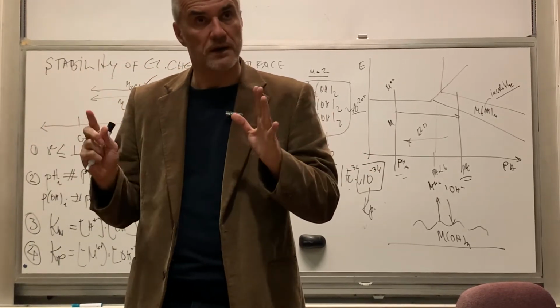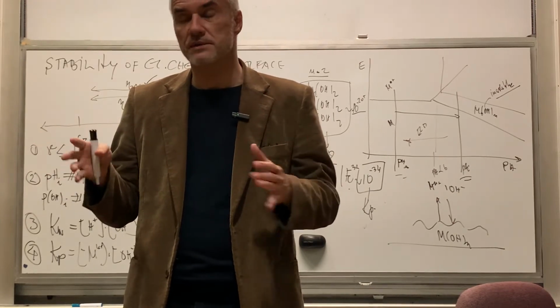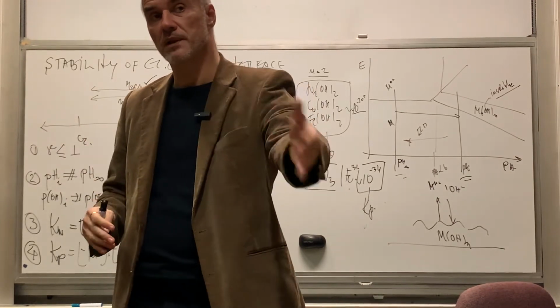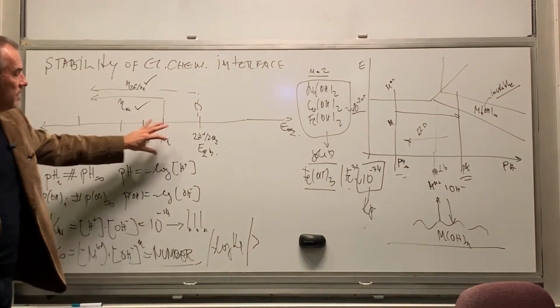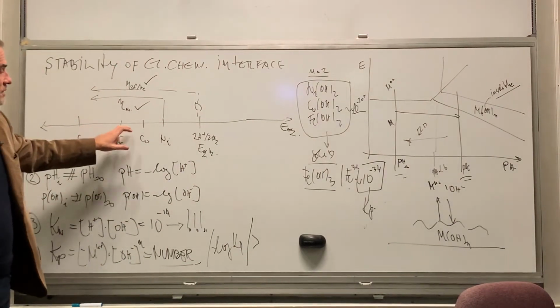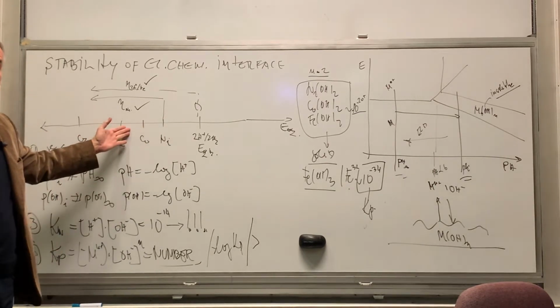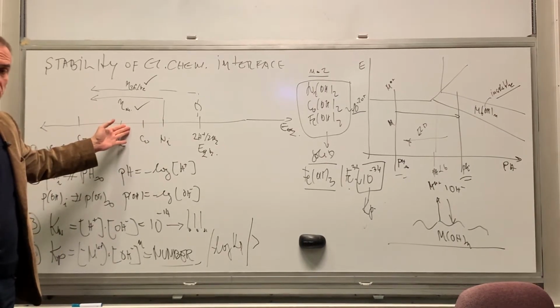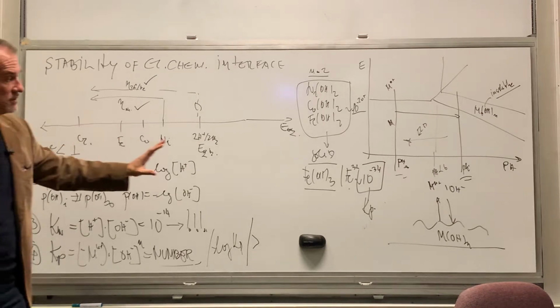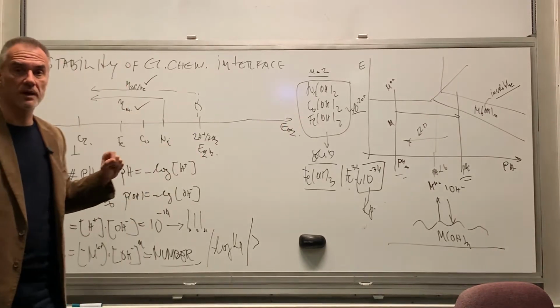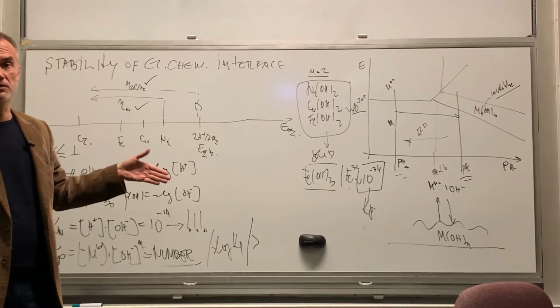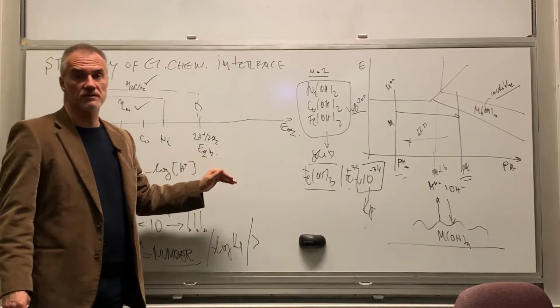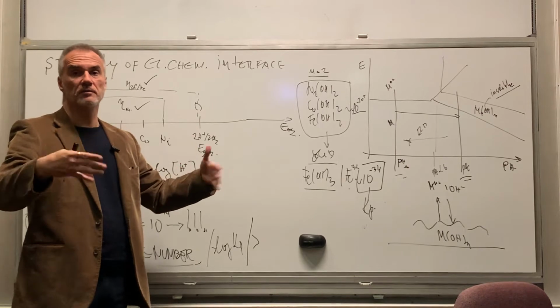So you have to be aware that electrodeposition does not necessarily always produce a pure metal deposit, but in particular when your metal has the equilibrium potential on the left side of hydrogen, it creates an opportunity for co-precipitation of insoluble hydroxide at the electrode surface while you're growing the metal film.